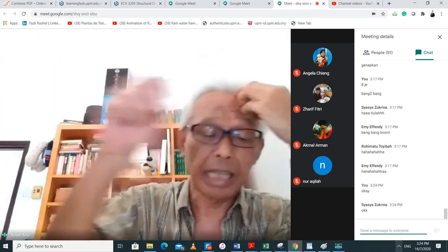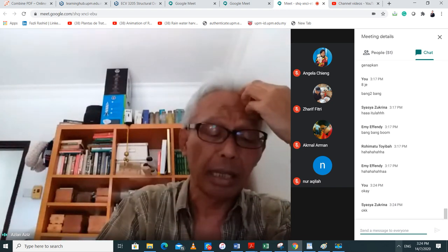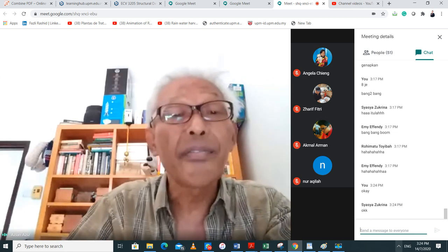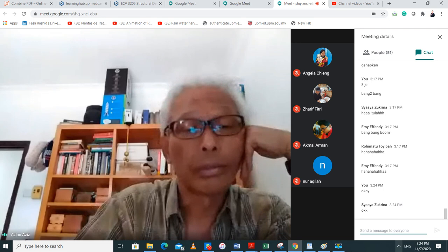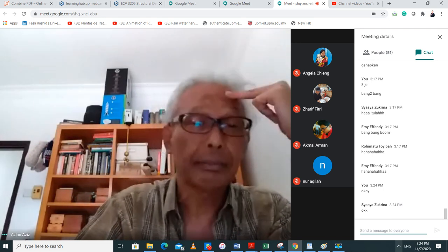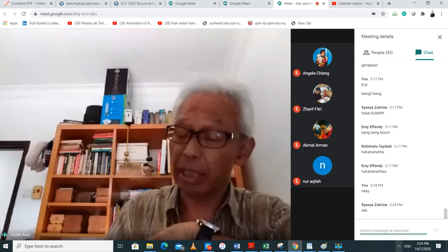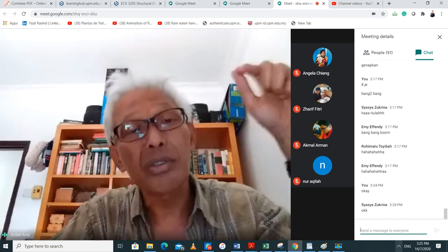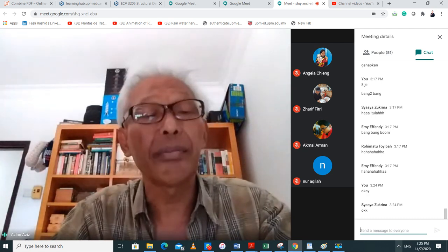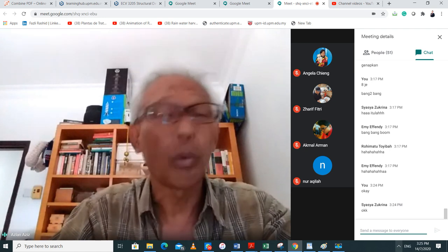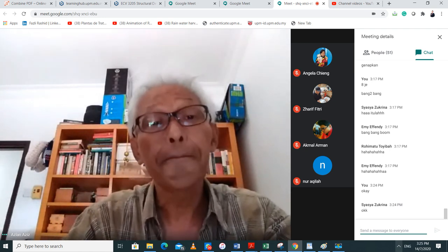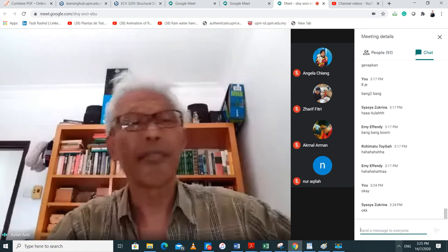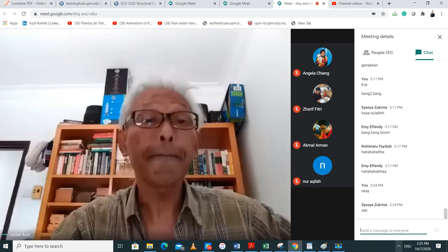So the load factor under compressive load is then 303,225. At that 10.2, you interpolate the value, you get 303,225. Compressive load is 650. Now the factor of safety you get is 5.0. See, you only need 2.5. A few minutes ago, you calculated minimum 2.5. 2.5 times 650, you say 1625 kilonewton. Now, because you want to take care of that uplift load, your factor of safety has increased to 5, only because of that uplift load. If there is none of this uplift load, you probably don't have to have a factor of safety of 5.0. Okay, good.